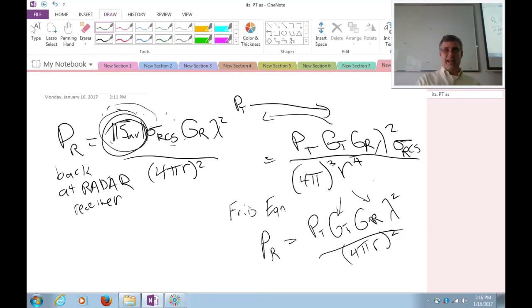especially when you get down to like AM radio where the wavelength is much bigger than your antenna. You can only make a very low gain antenna with a small amount of metal compared to the wavelength. So from that perspective, low frequency is always better because according to the Friis free space equation, I got a lambda squared in the numerator, which is effectively like having a lambda squared in the denominator.